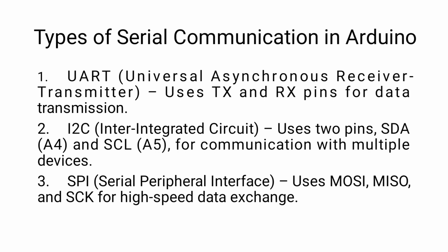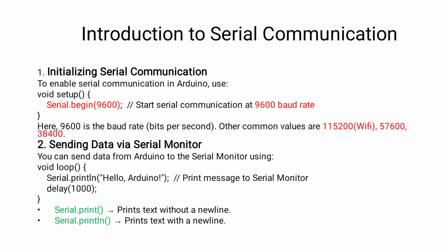Inter-integrated circuit uses two pins, SDA and SCL, which are A4 and A5 in Arduino, for communication with multiple devices. Serial peripheral interface uses MOSI (master out slave in), MISO (master in slave out), and a clock for high speed data exchange.